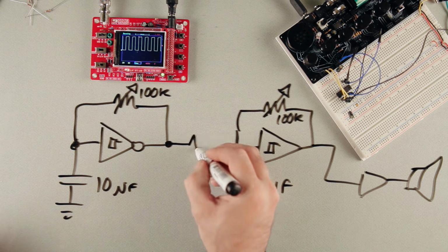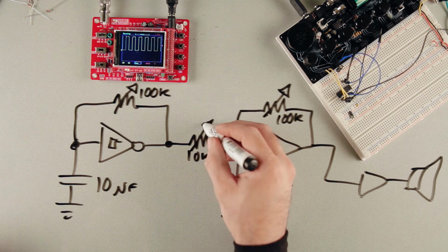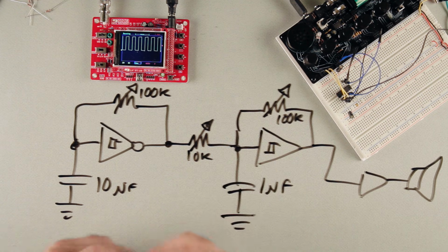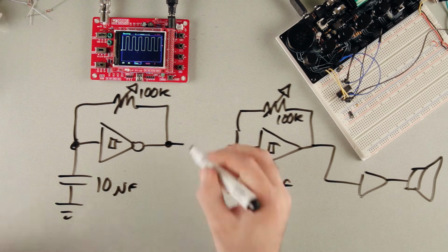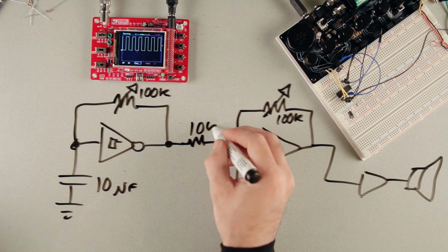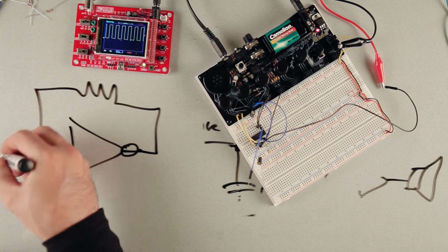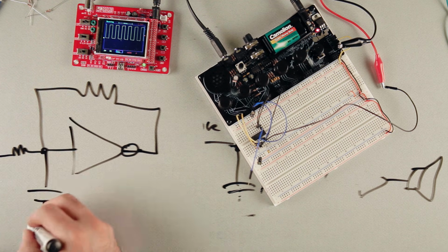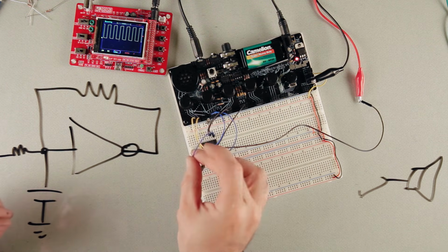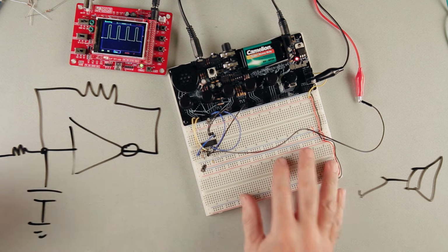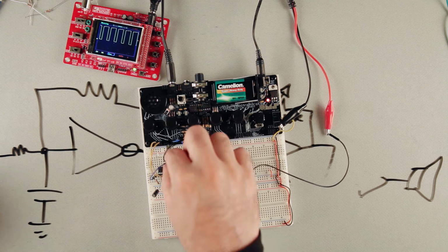And what we're going to do is we're going to run that through, you can run it through a resistor, a 10K, but we want to make it a variable. And this will modulate the pitch of that. Well, let's do that first. So I'm going to take the output of that one, I'm going to run it through a 10K resistor. So again, this is our audio oscillator, and we're going to add a 10K resistor to the input. This is the capacitor to ground. And then I'm taking the output of our other oscillator, so let's listen to it, and I'm going to plug that in here. And then you can hear the pitch going up and down. So that's an effective LFO.